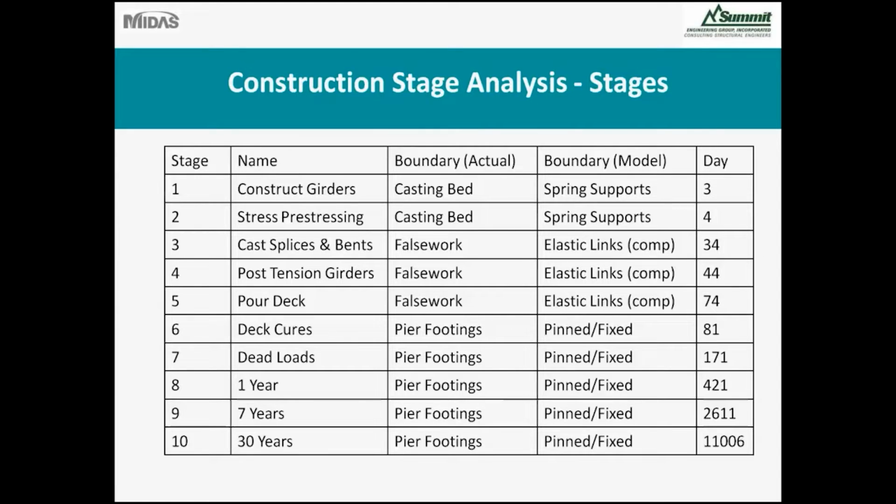Then, of course, there were the moving load analysis and seismic load analysis on top of that. The boundaries I used are shown in the fourth column here. I used spring supports for a casting bed, and then compression-only springs once I took them to the field to simulate shoring towers.